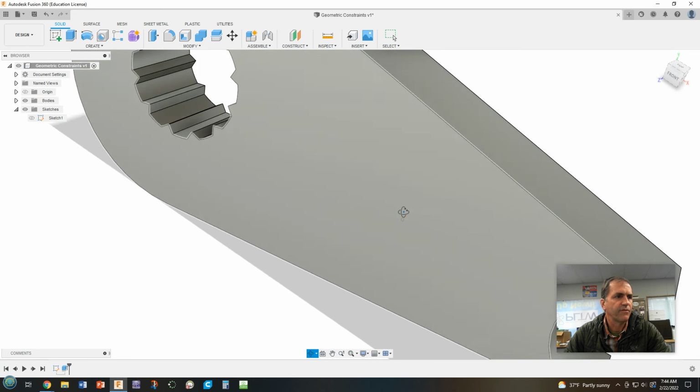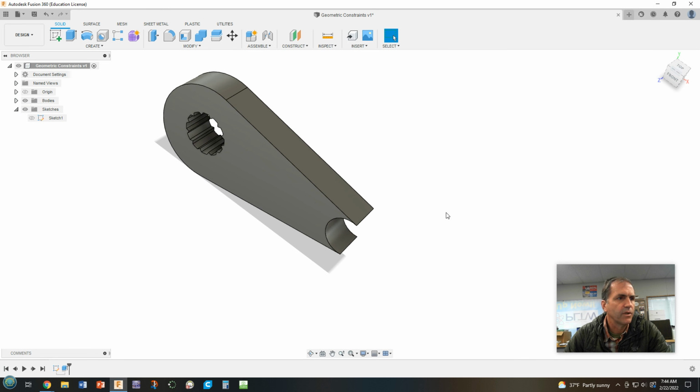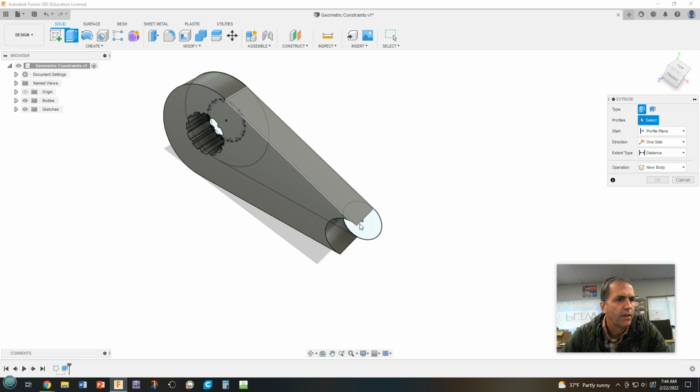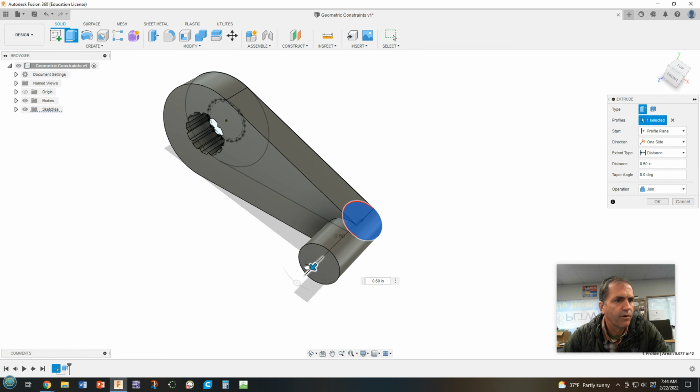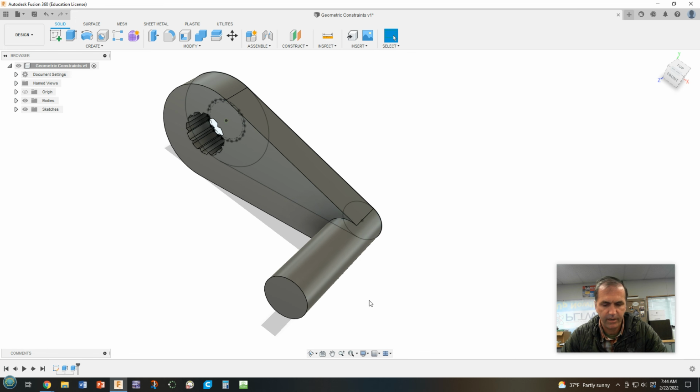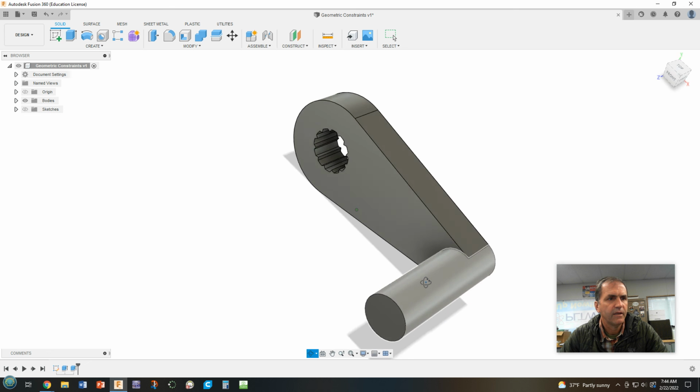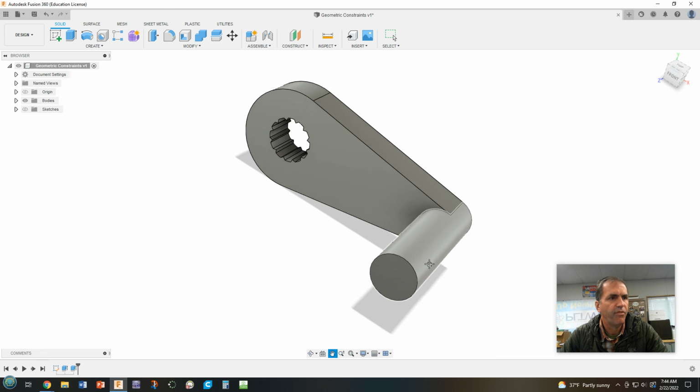We're going to make something actually very similar to this for the actual automata, but I need the part that we can actually crank. So next thing is we're going to turn back on our sketch by clicking the eyeball, expand sketches, turn on the eyeball for sketches, and now we're going to extrude just this part that we didn't extrude before out to about, I don't know, let's just go to 1. All right, and let's turn back off the sketches and take a picture of that.